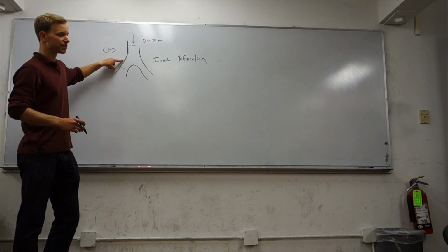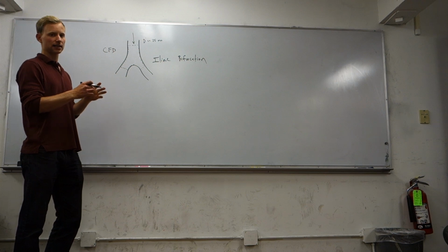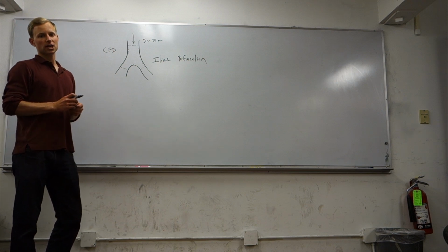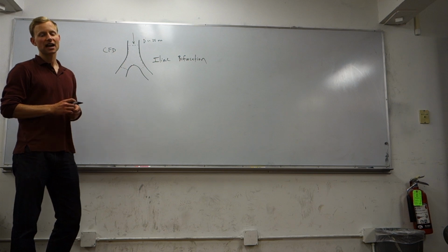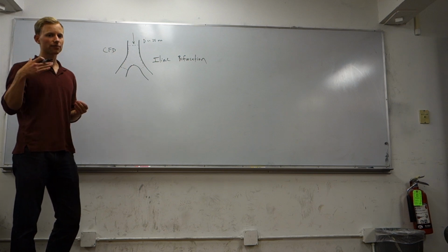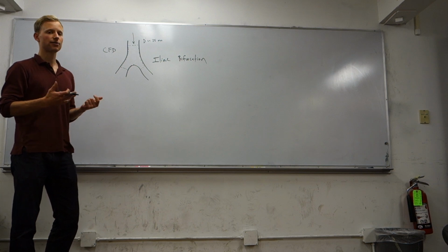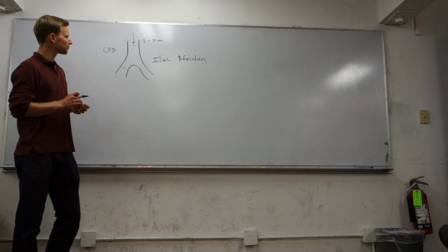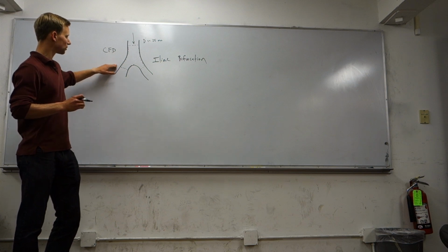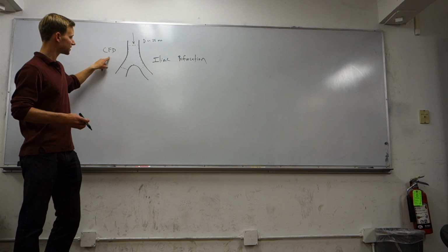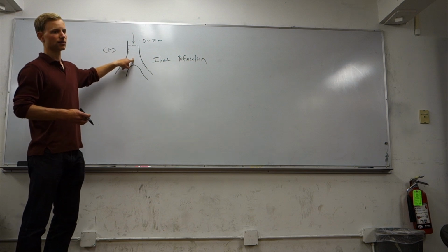The geometry might be changing in time as it elastically expands and contracts, and blood might not be the perfect Newtonian fluid. Blood is shear thinning, which means that as you apply a shear force quickly on the fluid, the viscosity decreases. So the viscosity is a function of the rate of shear. So it's a difficult problem, but it's still doable. And there's actually a lab on campus here which solves CFD. Using CFD, they solve for the flow rate in this region of the aorta.